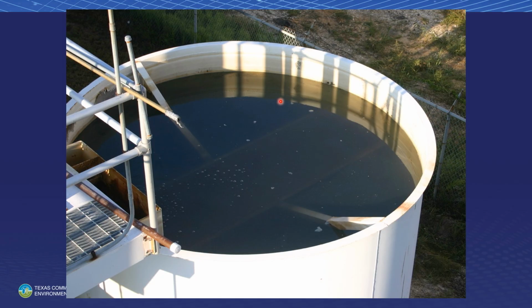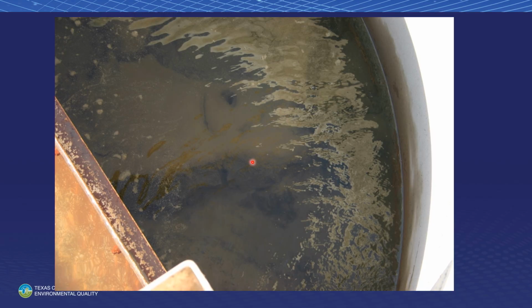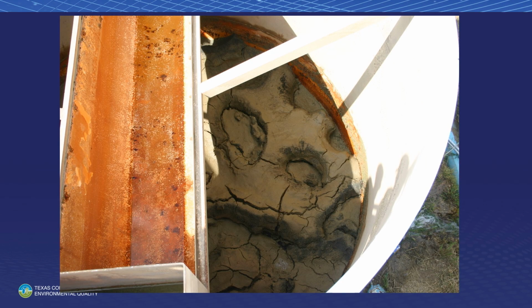This is a filter, not a clarifier, a filter. The filter is normally operating. You're looking down into the filter. We let the water drain down in the filter to below the backwash trough, and now the water, because we're draining the filter, doing filter inspection. Now the filter water is about 1.5 feet above the filter media, and you can tell there is no anthracite visible. There is mud visible. We continue to drain the filter down.